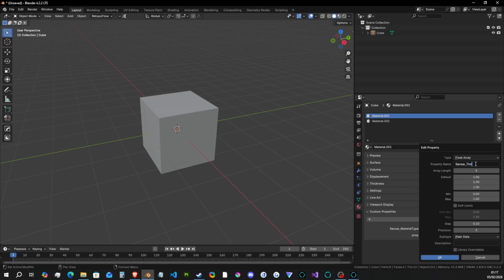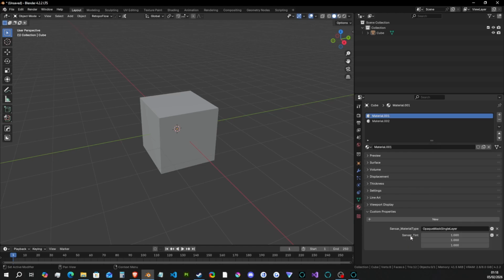You can type this in. Make sure there's no extra space on the end or anything silly. The capitals and the underscore are there. And this one's saying the minimum and maximum we need to change, as it can go up to 255, and we can leave it at that. You don't need to worry about any of these other settings. Precision would remove these extra decimal points, but you don't need to, you can leave it as is and press OK, and that's added a property. And that lets us just choose a new tint. Let's set this to something that's nice and easy to see.